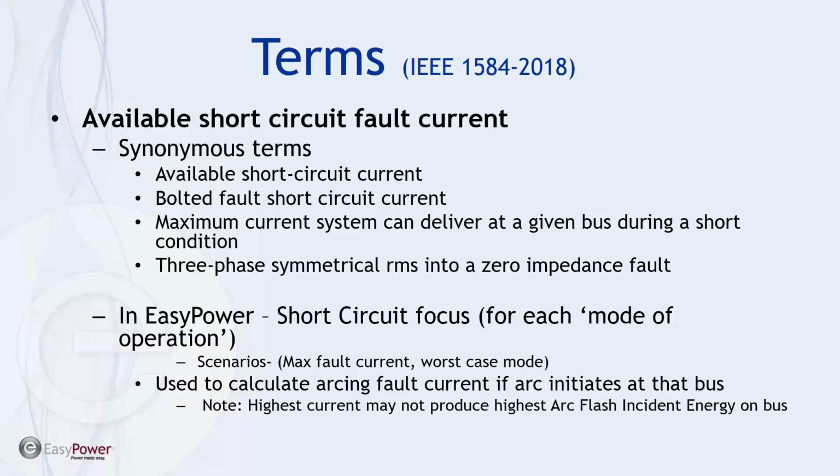He uses bolted fault current and doesn't consider the electrical and thermal properties and the influence of the plasma itself, which makes the calculations for arc flash results a bit more conservative if we're using the Ralph-Lee model.